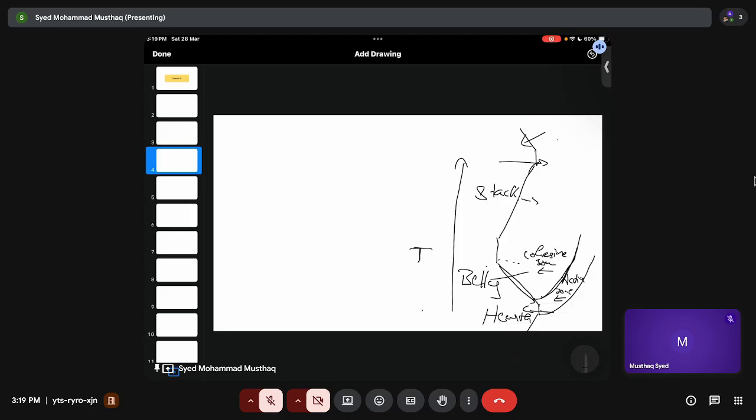Okay, you will have a contraction also, so that's why you call them a cohesive zone. And there is a dead zone here, this region. Why? Because the air is not available for combustion here, and the best part is that whatever coke is here just floats on your slag and liquid metal, right?